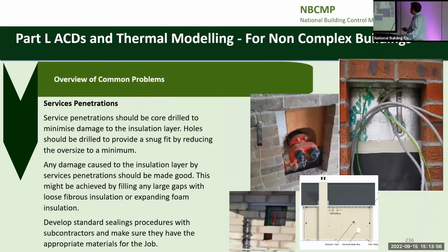Surface penetrations too. I've seen this one here, they were using a kind of box for a fire hydrant. It was very good. Insulation seems to cut out well, and it means they can come back in there and foam that out, and it's nice and tidy. So keep the holes and penetrations. And the other thing here, with the blown-in insulation that's becoming very popular, is your DPCs here. Ensure that there's a bit of rigid insulation there, so you're not drilling through concrete heads or structural elements, and you're forming that sloped insulation there so it drains the cavity.